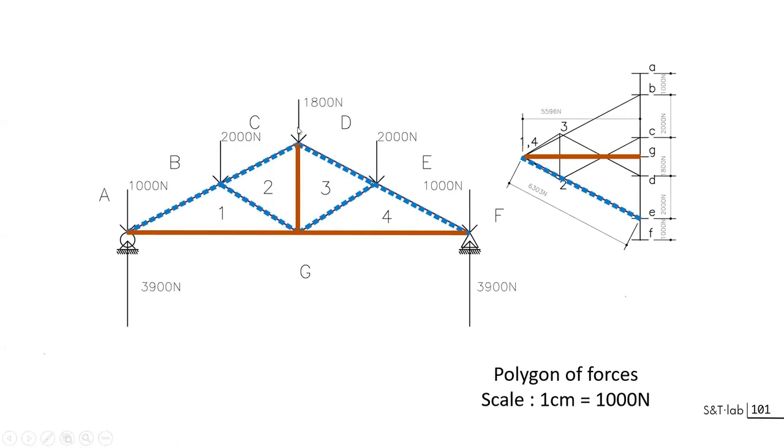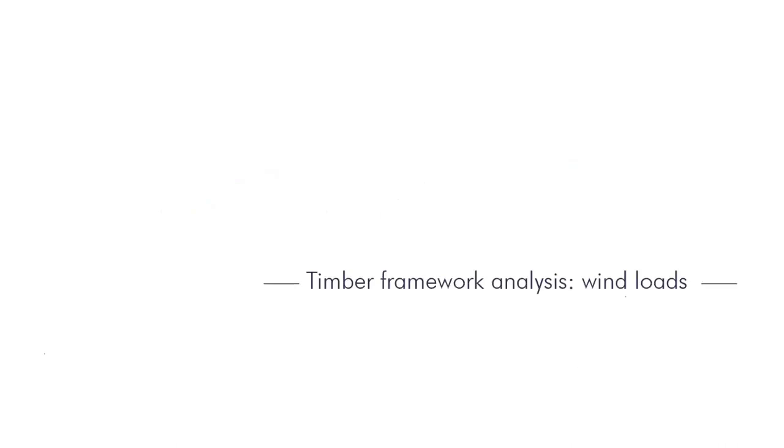For instance, here you have a force that is applied in the middle. If you push here, you are not able to sustain the system without this, so we'll have compression on both sides. This compression has to be equilibrated by tension, and here with this force we'll need 2 bars to equilibrate it. If you are pushing in this direction, we'll need this bar in tension. So that's easy to say in this case, but that won't be that easy for more complex systems, for which we need analysis.